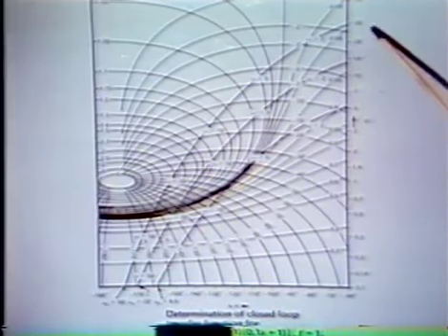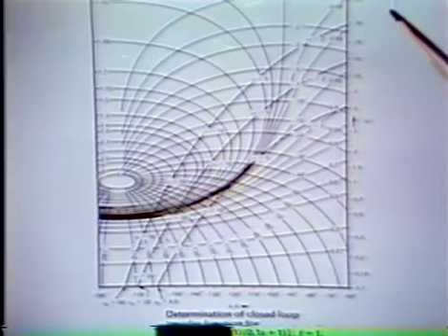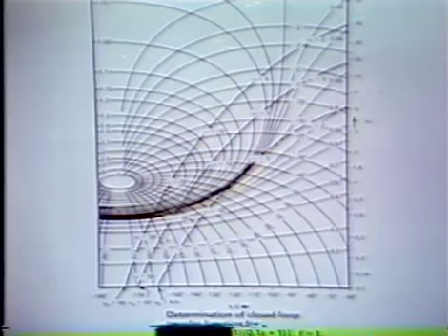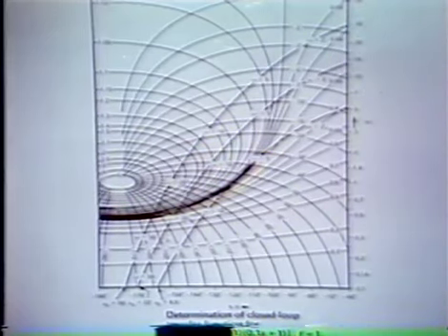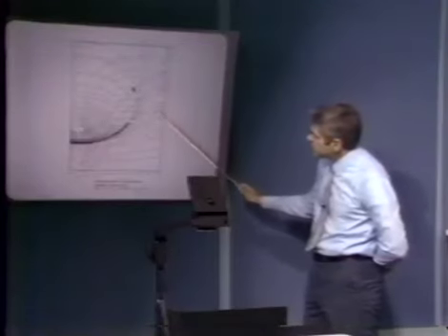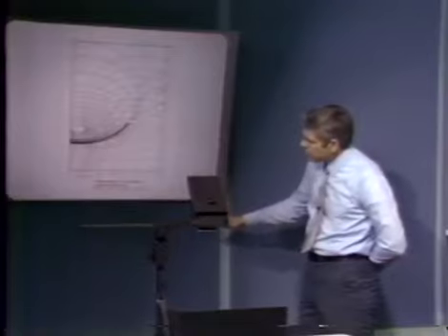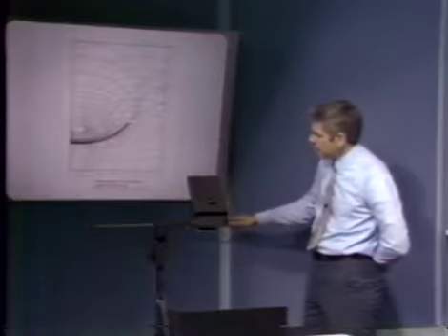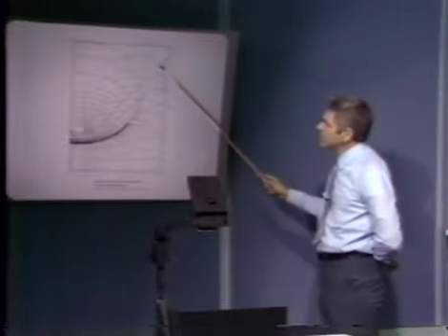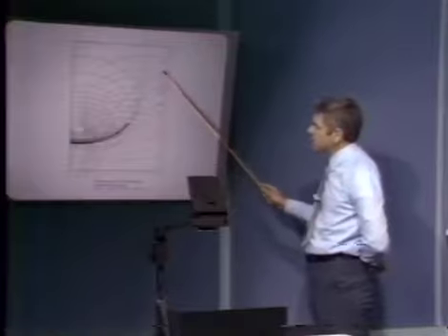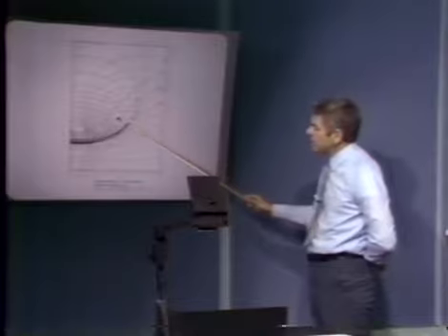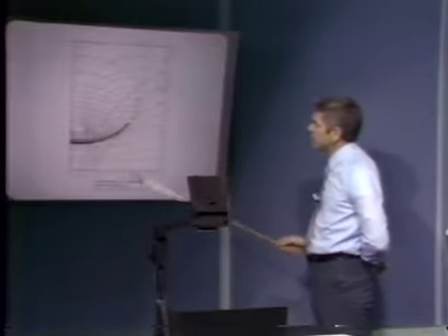These curves, of course, are effectively the left-hand part of the Nyquist construction. If we had the entire gain phase plane running out to 0 degrees here and did our Nyquist construction, we'd have a curve that did something like so, reached minus 180 degrees asymptotically, the contour would close this way and so forth. So what we have is simply the left-hand portion, or a piece of the left-hand portion of the Nyquist construction when we do a gain phase plot of the AF product.